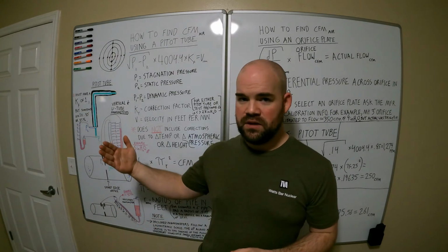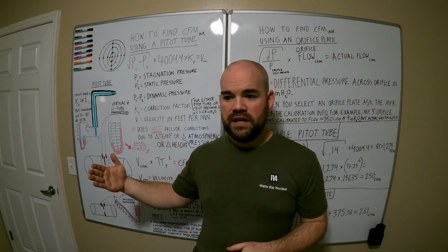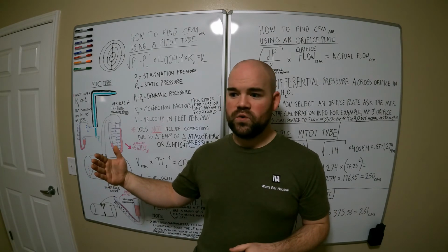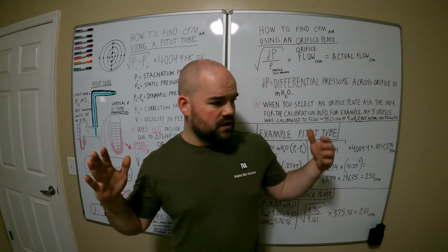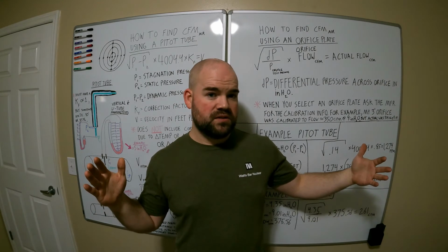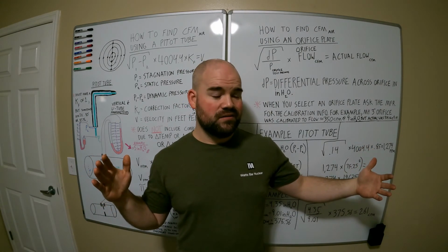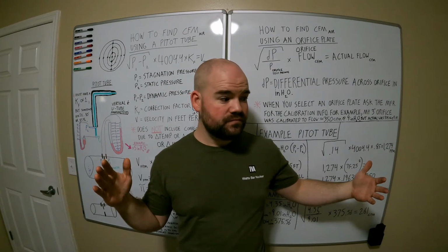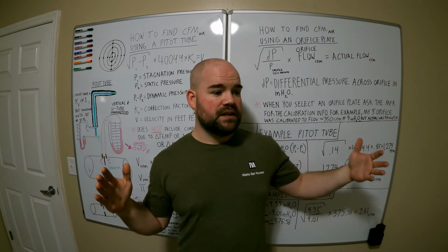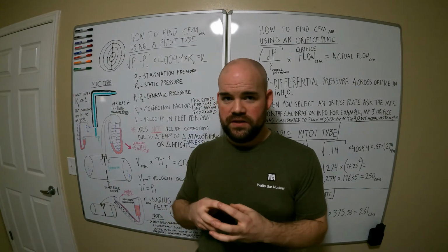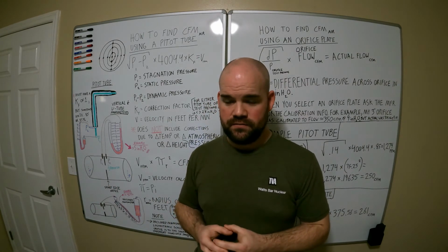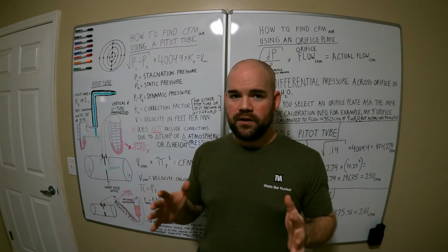If I have 15 pounds of boost on one car, it could add 350 horsepower, who knows? If it's on another application, 15 pounds of boost on a stock 350 small block is only going to be worth like 80 horsepower, maybe a little more. And that's because of the CFM that the engine is breathing, okay? 1 cubic foot of air doesn't change.